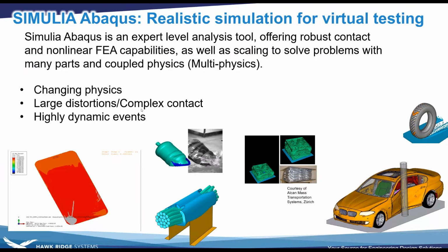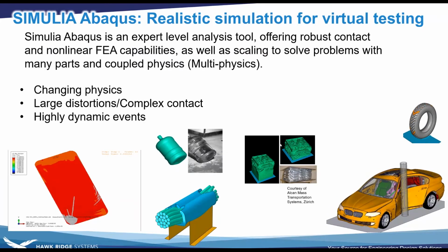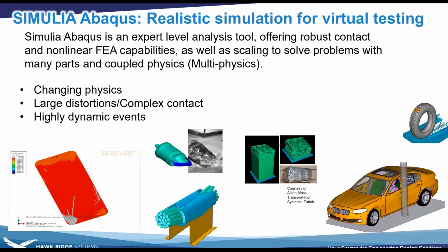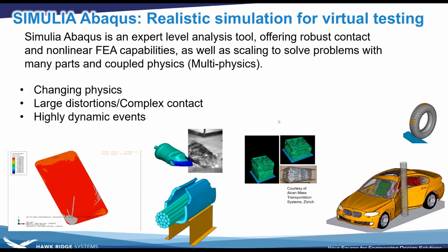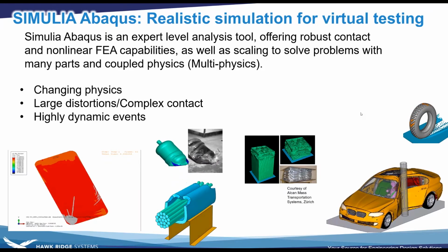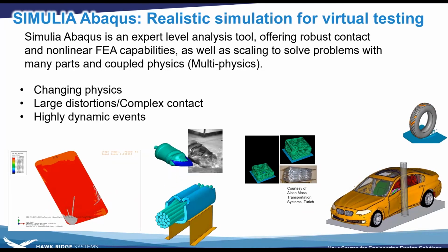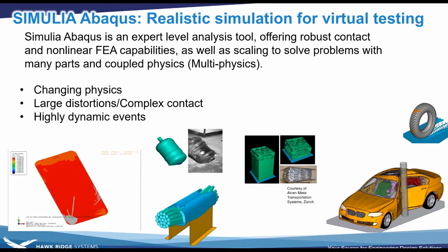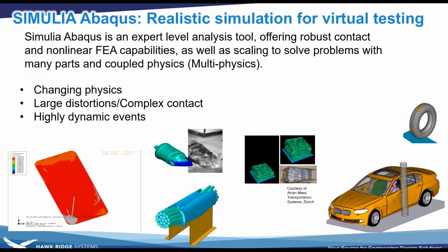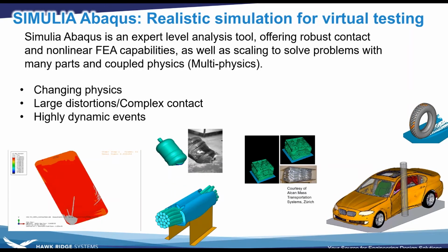And I want to go through some of the areas where SIMULIA has a strong point in these analyses, where we go through forming and self-contact. You can see in the example in the center of the screen with the collapsing tower that we've got a lot of areas where we have quite a bit of deformation and self-contact as that buckling occurs, and a pretty nice match to the physical test on the right for that energy barrier.